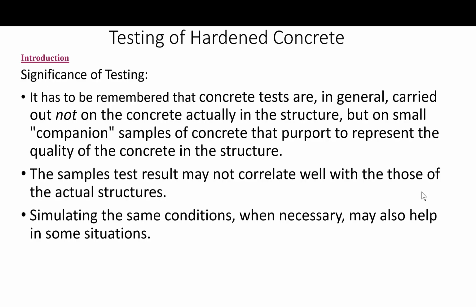Rather, concrete design is based on the implicit assumption that if the concrete has been placed, compacted, and cured properly in the structure, and if the test results are satisfactory, there is a very high probability that the material in the structure will behave in an adequate manner. That is the approach. This is quite different from the common assumption that we actually know or measure the mechanical properties of the concrete in the structure.